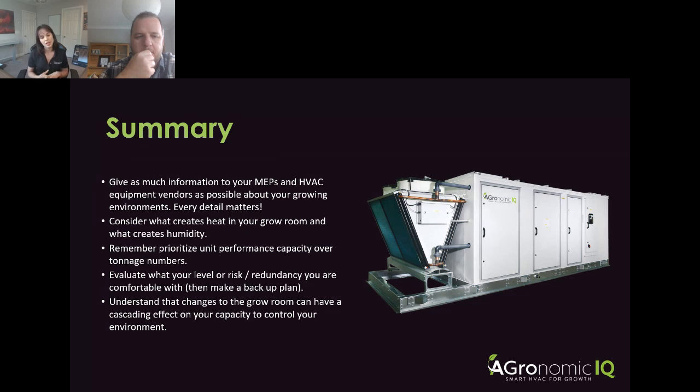Remember to prioritize performance and capacity over tonnage numbers. So if two equipment vendors are coming and saying, hey, we both have two 70-ton units, make sure that the performance at your conditions is meeting what your load is, because it's not always an apples to apples comparison when it comes to outputs.